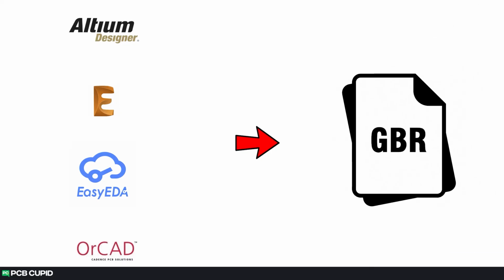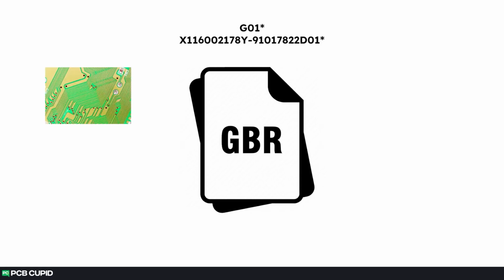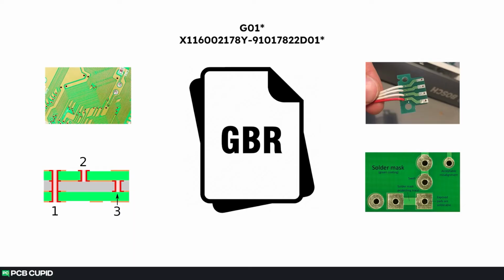There are hundreds, if not thousands, of different designers and companies that use various different ECAD software. It's very hard for manufacturers to be expert at each one of them and use the data from the project file for manufacturing. So most of the final design files are converted into a Gerber file. So what's a Gerber file? A Gerber file is a collection of different files containing design information and vector coordinates of copper traces, vias, pads, solder mask, and silk layers.